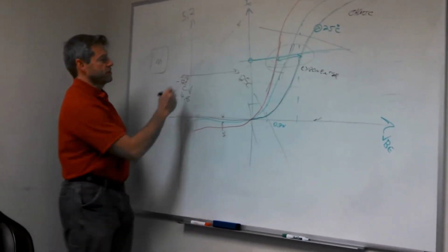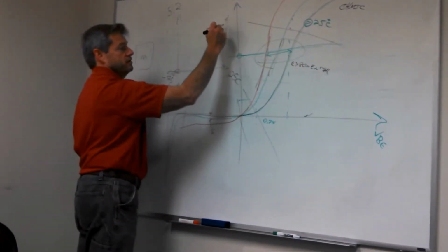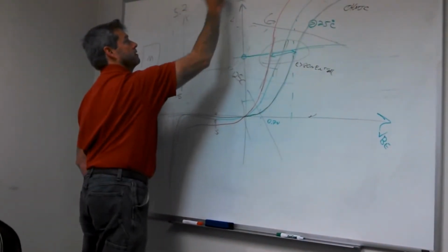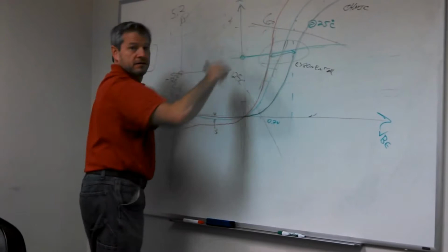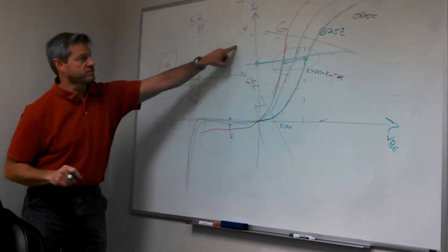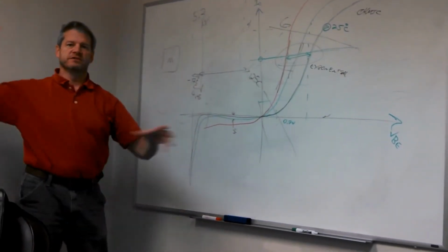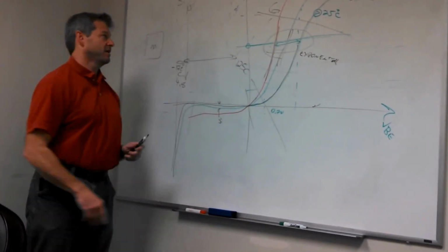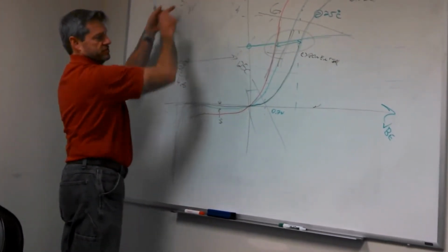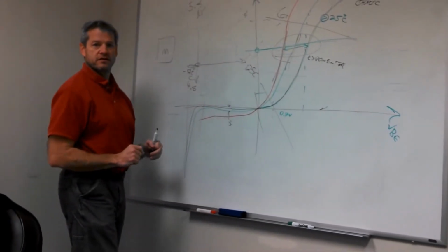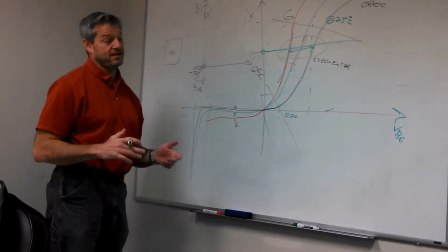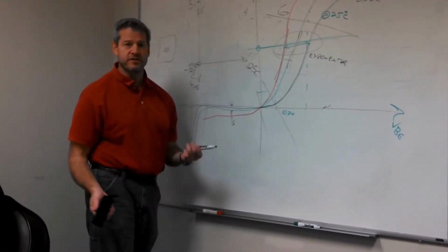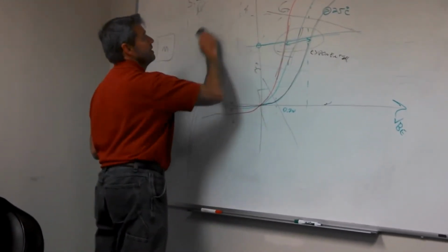You start talking about corner testing. You've got to hit this corner, you've got to hit this corner, you've got to hit all the corners in your testing to say it works in all these different possibilities we can get. And that can be onerous and painful. So sometimes we wave our hands and say, well, it worked at these two extremes together, and these two extremes together, everything's fine. Well, I've been bit by that. It's rare that you get bit by that, but I've been bit by it.